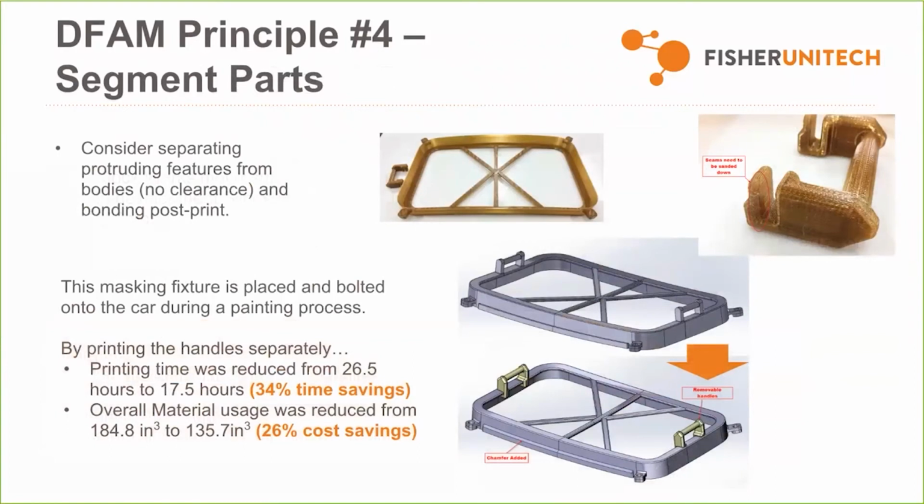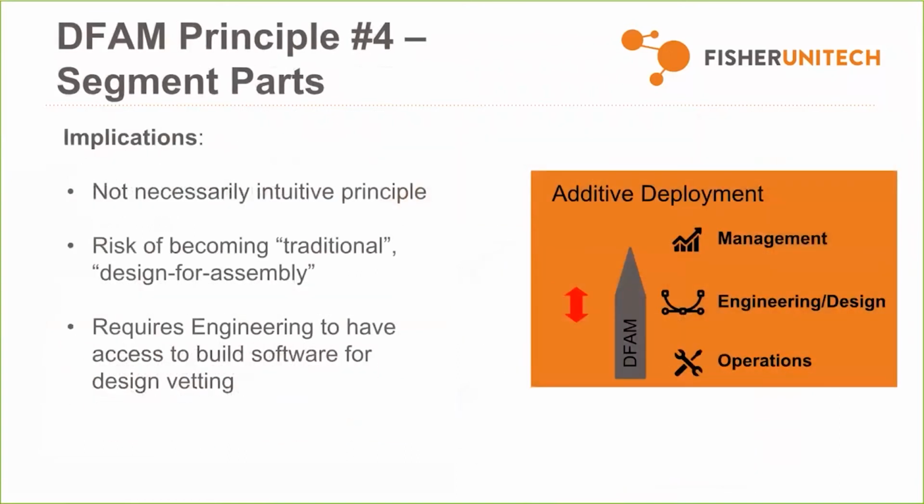The one takeaway with that is you have to make sure that it doesn't become a traditional kind of design for assembly process. Sometimes we've seen clients who start to segment the parts almost to an extreme where lots of assembly time is then required again, and some of those benefits are negated. So just make sure that as you're doing that kind of segmentation, you don't go overboard.